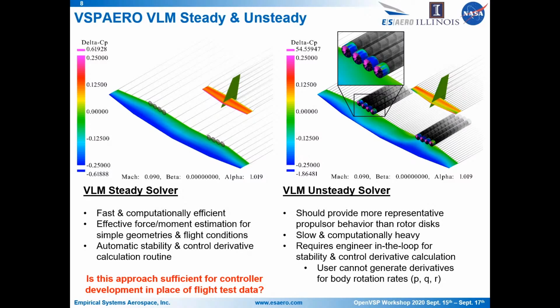So there is a fundamental difference in time scales that you have to look at. And from the aircraft dynamics standpoint, the propellers really are a time averaged actuator disk kind of thing when you're looking at the rates of even short period and phugoid. And so you need tools that are mixed.